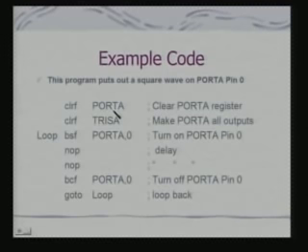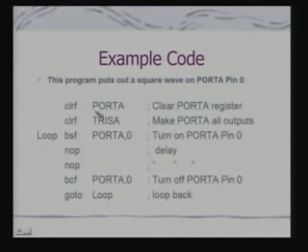The next thing is, these ports can be I/O ports. That means each pin can be configured as an input pin or as an output pin. Now, if you are doing that, then I need to pre-program that port and each pin of that port. So, in this case, we use a register called TRIS, and for each port, since we are talking about port A, we have a TRIS A register, and we are clearing the TRIS A register, making all pins of port A output pins.